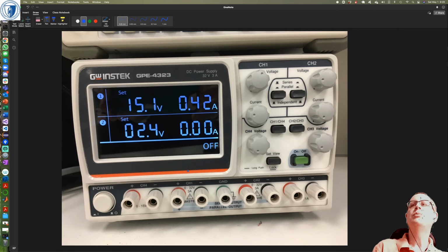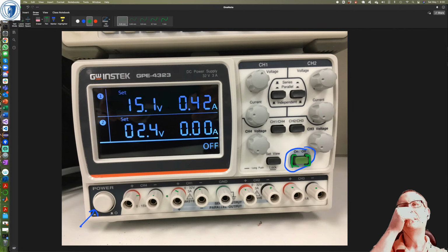And this is one of the power supplies. Obviously there's the power button where it says power, but these things around the green button light up when there's actually power coming out of the device, right? So you connect up red, green, red, black, red, black, red, black, red, black. And here you can see, at least for channel 1 and channel 2, you can set the voltage, but there's also a current limit on there as well.